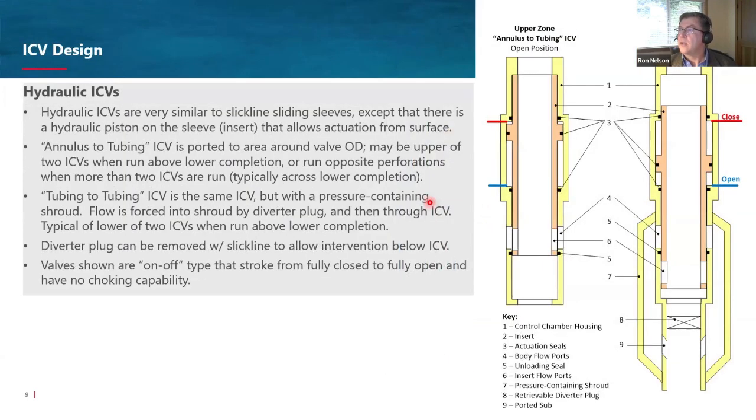I touched now on the hydraulic ICVs. Again, I'll go through a few designs, but the hydraulic ICVs are definitely the workhorse of the industry. The vast majority of what's been run out there are hydraulic ICVs. They're very similar to slickline sliding sleeves. In fact, I think they evolved in many cases from slickline sleeves. The key difference being that there's a piston on the insert.